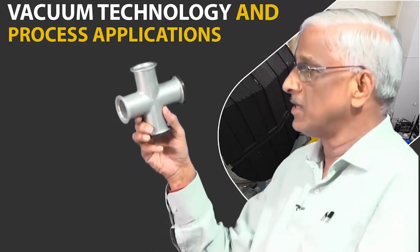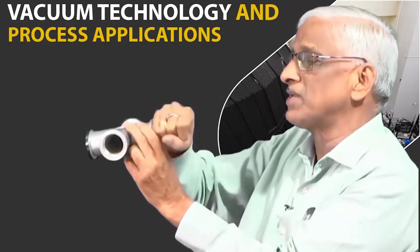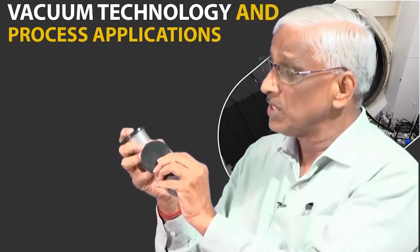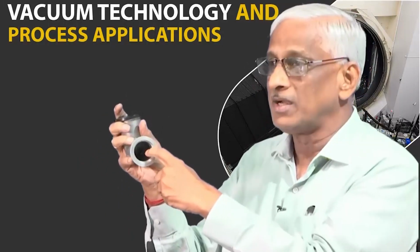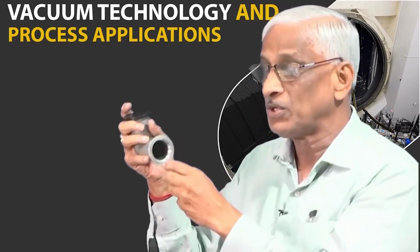Friends, after discussing components, I thought of showing some components that we have in our laboratory at IIT Kharagpur. For example, I told you a cross. These have 4 flanges, so you can make different connections at various points. Then you have a T connection. Similarly, you have an L connection. And how do you choose? L means wherever you require an L type of connection, but the dimension has to be DN 42, DN 25, that means 25 millimeter or 42 millimeter, you have to specify.